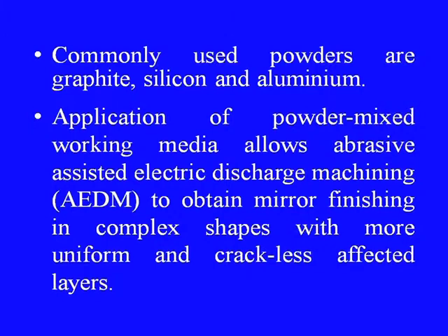Commonly used powders in this process are graphite, silicon and aluminum. Application of powder mixed working media allows abrasive assisted electric discharge machining (EDM) to obtain mirror finishing in complex shapes with more uniform and crackless affected layers.